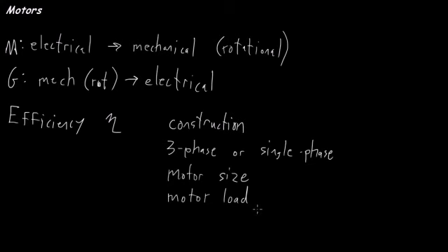And in the notes, I provided you with a table that gives standard efficiency numbers for various horsepower sizes of motors from 1 to 100. And you can see there's a standard and a premium efficiency. So you should check the notes for that. Just be aware that typically there's an extra cost associated with a premium efficiency motor. So one of the things you can look at is, okay, if the premium efficiency motor costs more to start with, how much money does it save me over the lifetime of the motor in terms of energy costs? So I think you'll find that depending on the type of motor, a lot of times it's worth it to go with the premium efficiency motor. Even though it costs you more initially, you can save money in the long run. That's the type of thing we will study quantitatively in the fall with energy investment analysis.